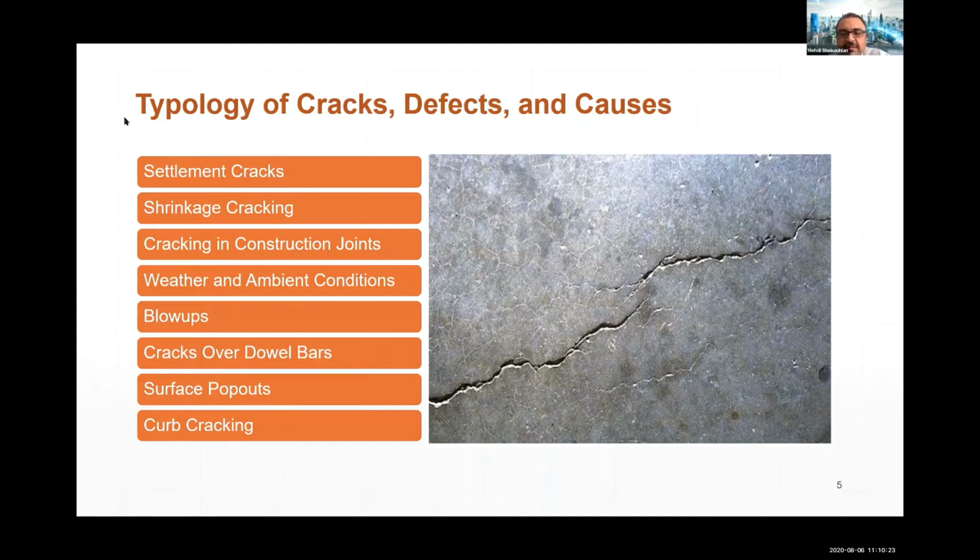Like all materials, concrete also expands and contracts with variation in temperature. So concrete shrinkage, which is basically due to the temperature at the early age of the concrete, is also very important to consider. The concrete slab cracks when tensile stresses within the concrete overcome the tensile strength.